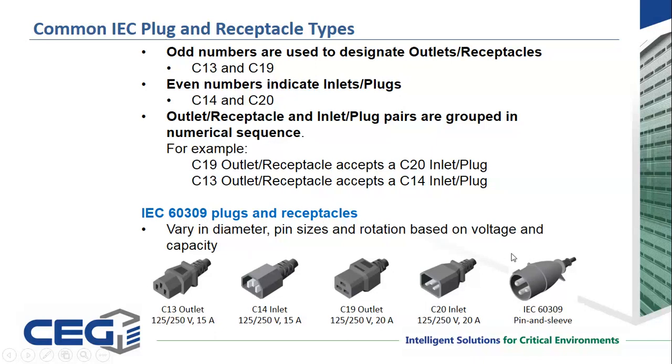This guy down here in the bottom right is what's referred to as IEC 60309. It varies in size and diameter, but this is how very high-powered configurations are enabled, right? These things look like the end of a fire hose. They're probably in the hundreds of dollars, sometimes up to $700 just for the actual plug you see here. It could be 3 or 4 inches in diameter, have a watertight seal, and huge connectors. Because when you're running high amperage, you're talking large gauge wire sizes. The diameter of the cord may be over 1 inch, just the cord itself.